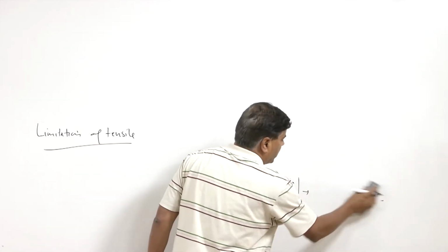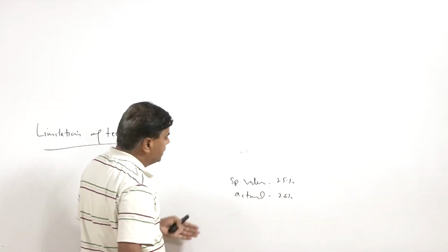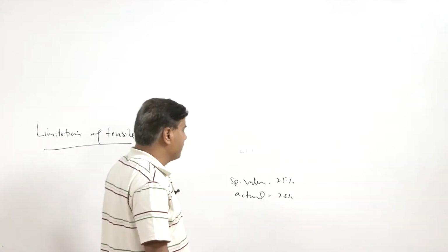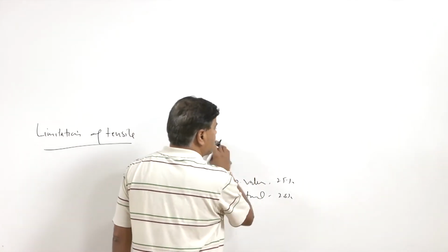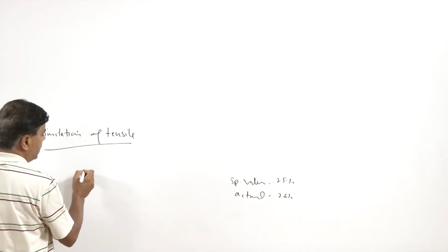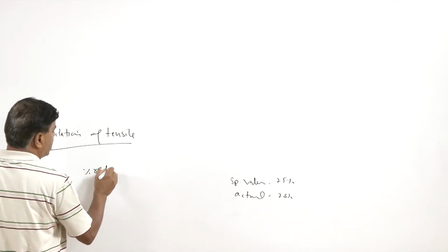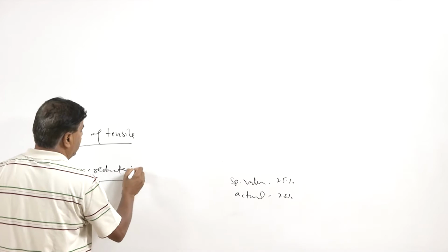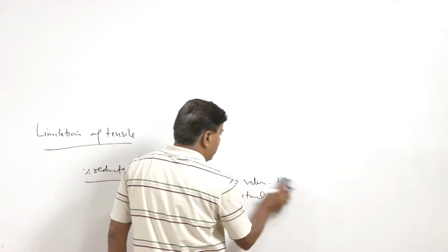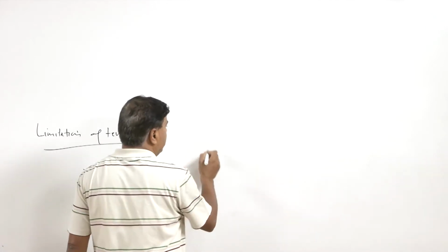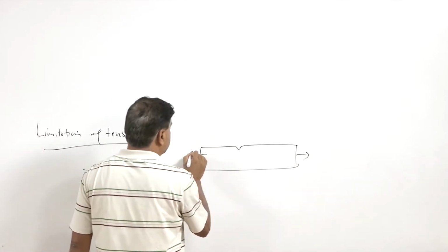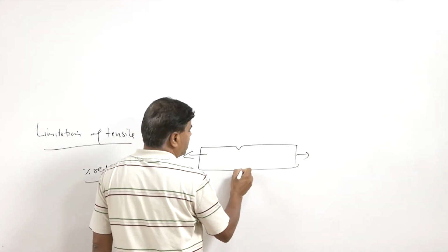So, what is the inference or interpretation here? Despite having good ductility, the material is still failing in a brittle manner. So, what is suggested is that instead of the ductility, it is probably better to assume that the percentage reduction in cross-sectional area can be the better indicator. Percentage reduction in area can be a better indicator of ductility, where even if there is a notch of this small size, under the external load conditions, to what extent the reduction in area is taking